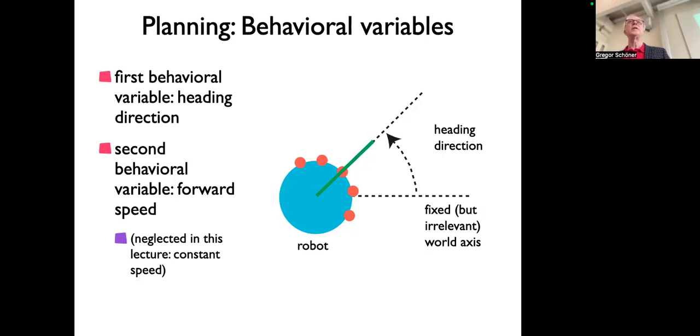So the other variable is the forward velocity. If you think of a robot with active wheels, the one is essentially a function of the difference of turning rate of the two wheels. If the sum of the turning rate of the two wheels is 0, then it's rotating on the spot. And the speed is the average of the turning rate of the two wheels. And there are some coefficients in there that have to do with how large the wheels are and how wide the vehicle is, right? That's in practice all the kinematics.